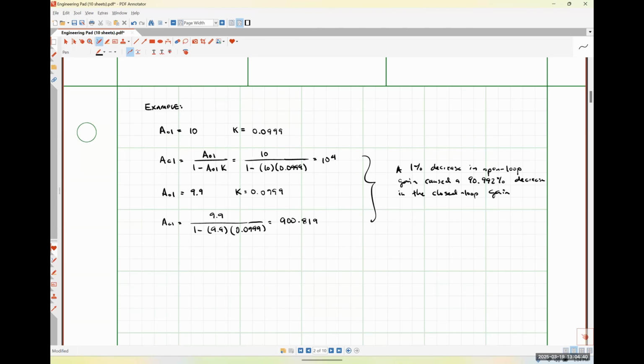Okay. So it's still going to provide amplification, but it's not going to provide necessarily a consistent amount of amplification, which means we need to use these positive feedback networks for applications where we don't need the gain to be consistent. We want things to either be VCC plus or VCC minus. If we're trying to have any control over it, positive feedback is particularly bad.